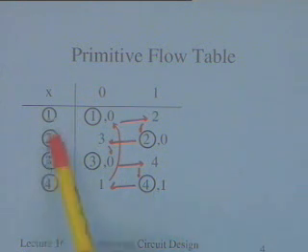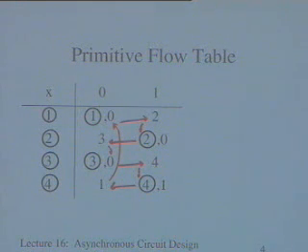Because there is no reduction possible, I have 4 states and I need to encode them. So now I have 4 secondary states also. I need to encode them, and I need at least 2 secondary variables to encode them. Now how do I encode these using these 2 secondary variables?